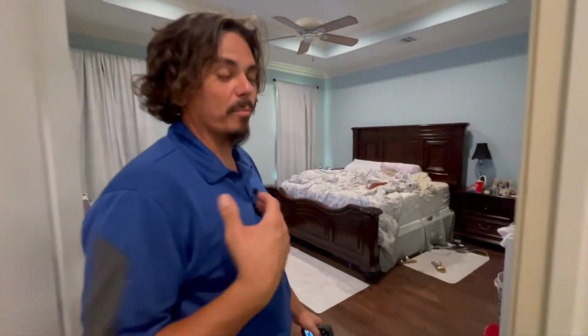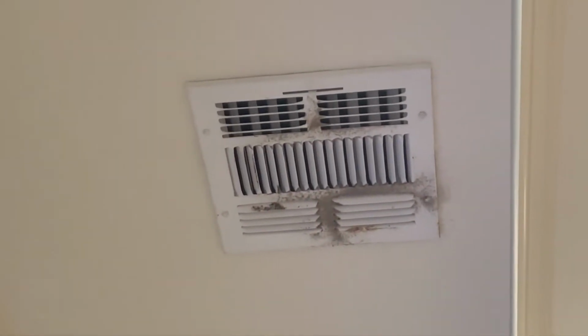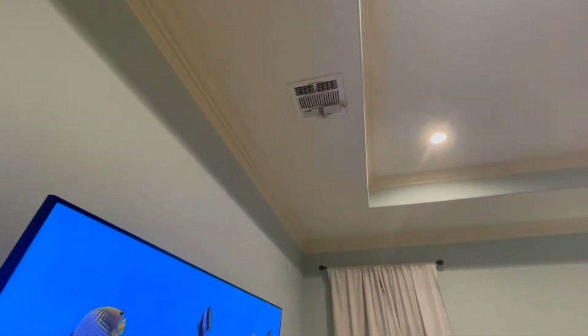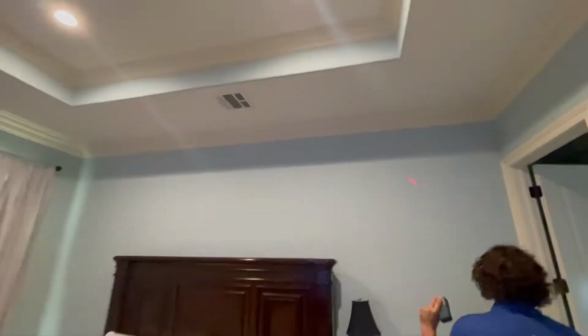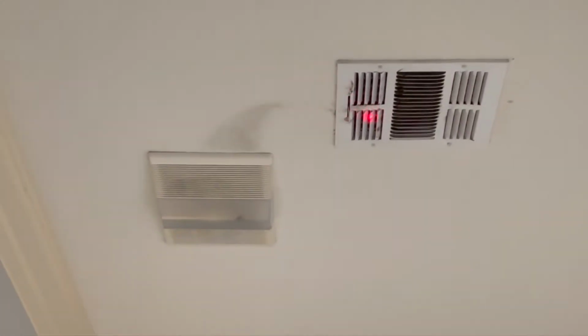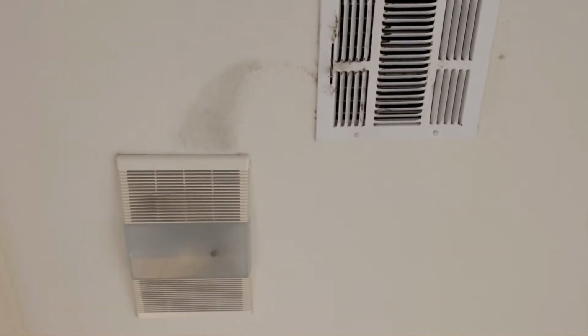Going back to using your senses, it's musky in here. You've got a considerable amount of buildup on these grills. Now, if they're using poor filtration and the humidity's high, a lot of that dust will stick to those surfaces. Interestingly enough, we can see here we have a supply air outlet and a bath fan, and if you follow that, that's a neat little line showcasing the leakage that's occurring at those sources.